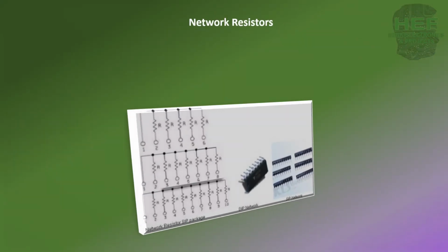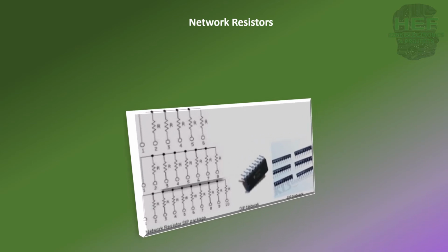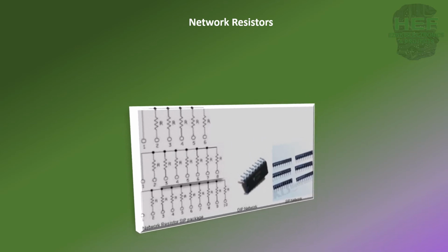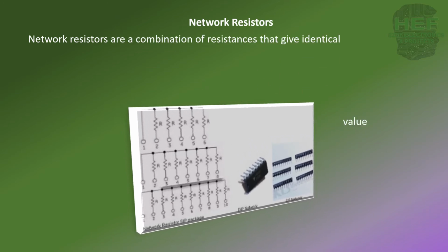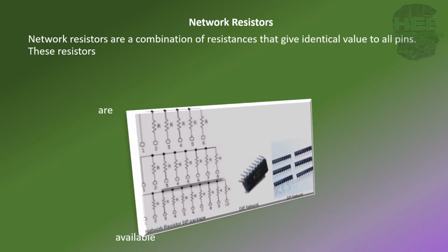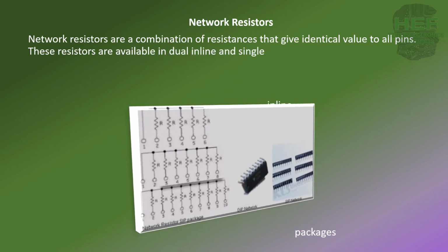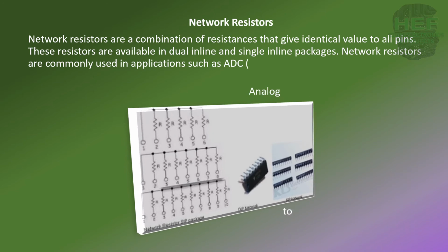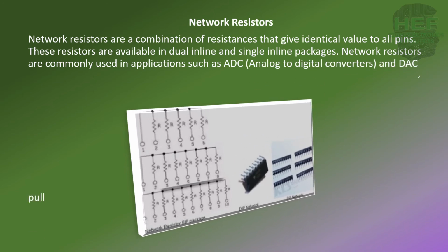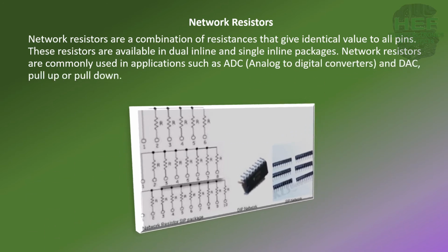Network resistors. Network resistors are a combination of resistances that give identical value to all pins. These resistors are available in dual inline and single inline packages. Network resistors are commonly used in applications such as ADC (analog to digital converters), DAC, and pull-up or pull-down.